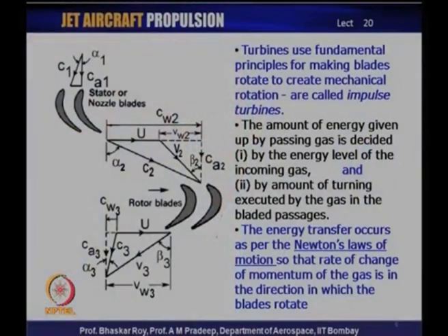So, in the process of this velocity vector that you see here, the flow C2 we have just seen has gone sonic. It may be, after leaving the stator, slightly supersonic, but the velocity V2 is actually subsonic, and this conversion happens due to this vector diagram here, that C2 gets converted, a supersonic or definitely a sonic C2 gets very naturally converted to a subsonic V2, with which the flow is going into the rotor.